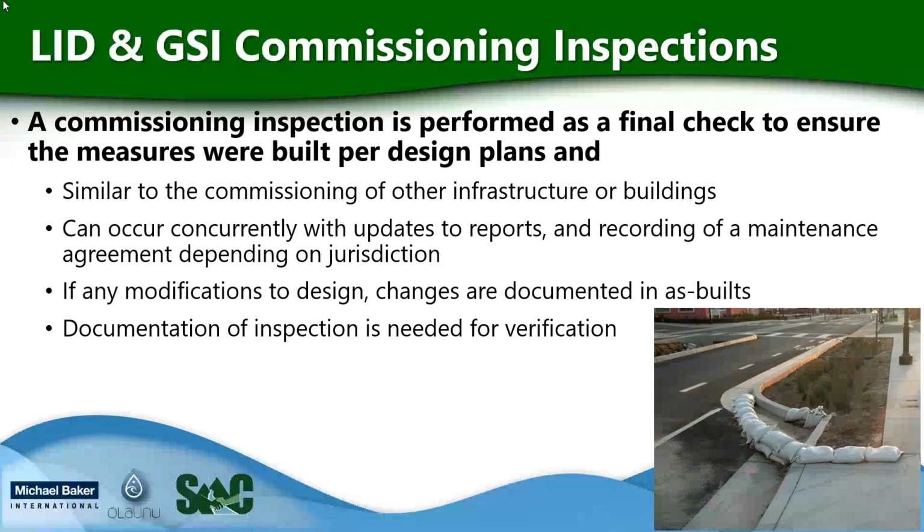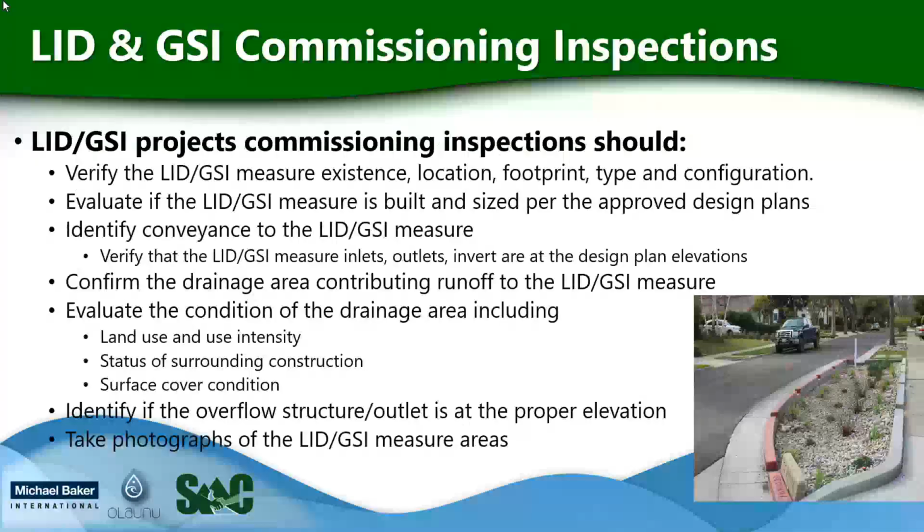Additionally, commissioning inspection should verify the existence, location, footprint, type, and configuration of your LID and GSI measure. Evaluate if the LID and GSI measure is built in size per the approved design plans. Identify the conveyance to the LID and GSI measure, and verify that the measure inlets, outlets, invert are all at